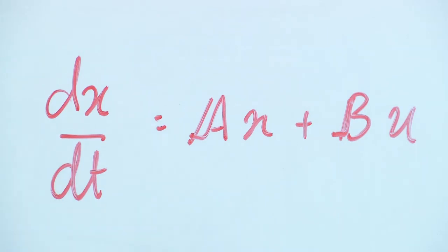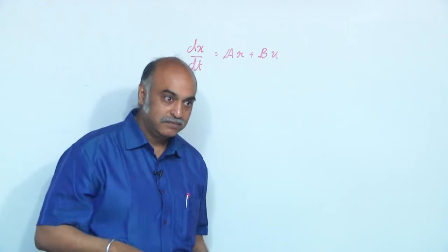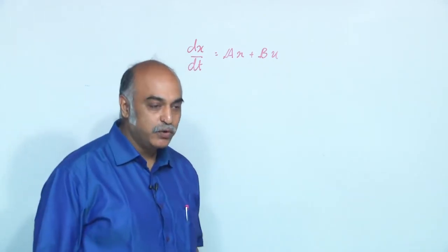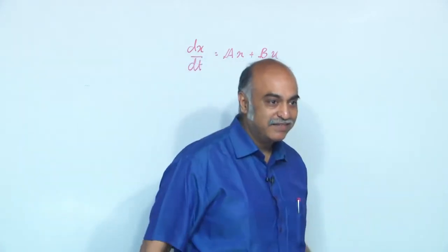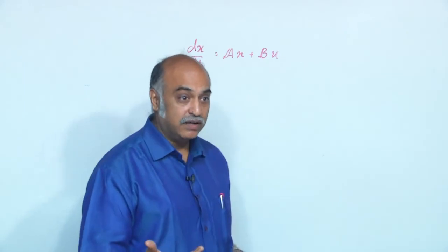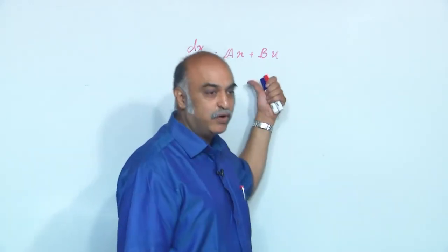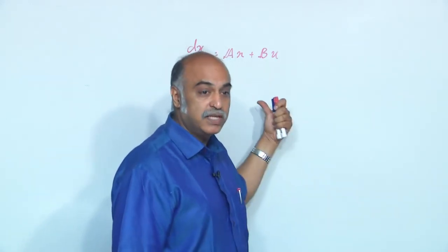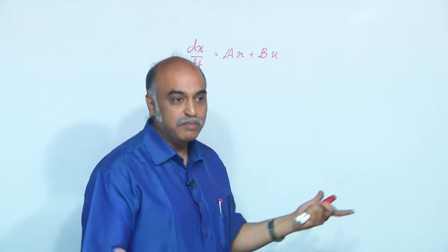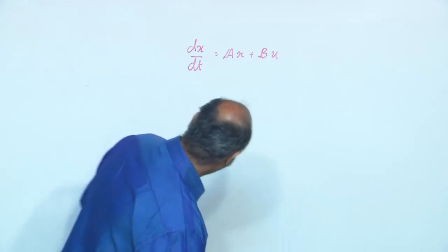In the limit as delta t tends to 0, which means as that tends towards now. But always you are talking of some future point, t0 plus. T0 plus cannot be there, right. So, you can never have it, and therefore, it does not exist, and therefore, any system which says d by dt cannot exist, and therefore, it is not permitted. Get the point? It is an a-causal system.